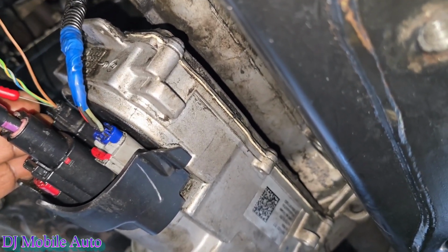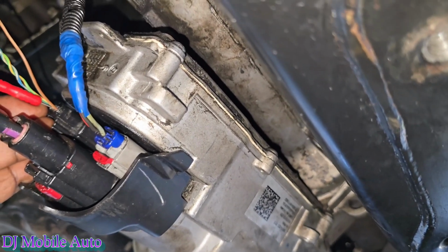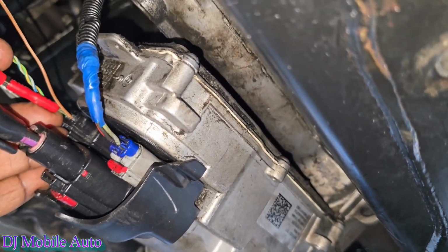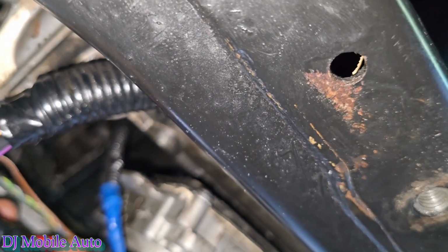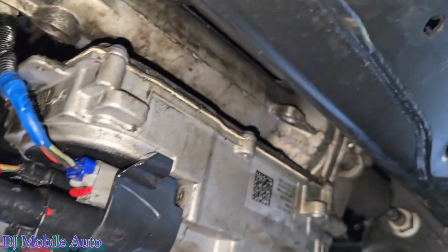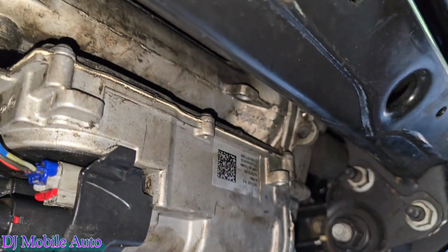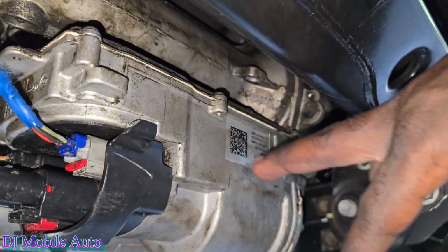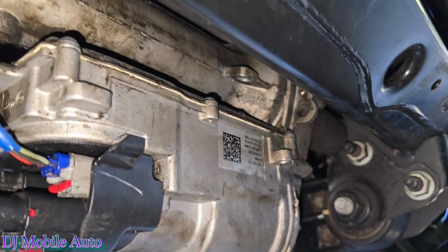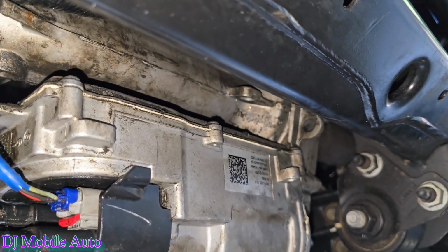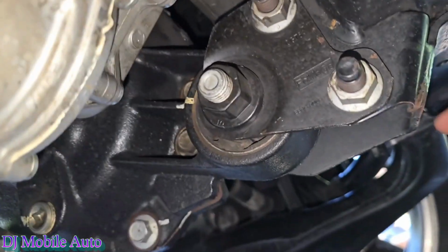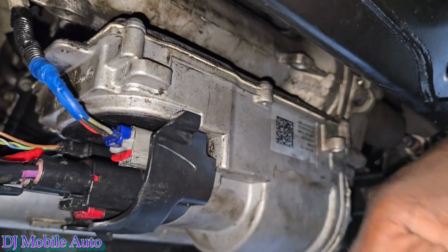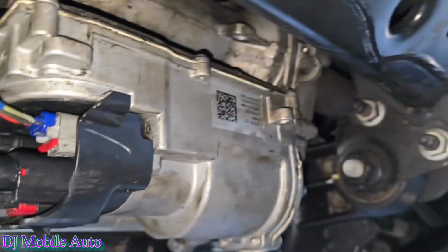I'm definitely going to scope it, right? And I'm going to put the pics up of what I'm seeing. But let's see if we could get in and see if my network is good, because it's not a lost communication. It's just saying that the control module is acting up, and if they have to replace, they gotta replace this complete steering rack, because it comes with this motor and the module is built on. And from discussing it with my boys, what they let me know is that because the motor is so low, basically it's right there, so if you're going through water and stuff like that, this is definitely gonna fail, right?